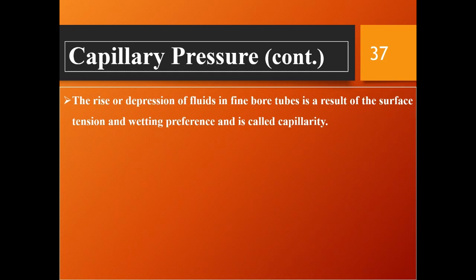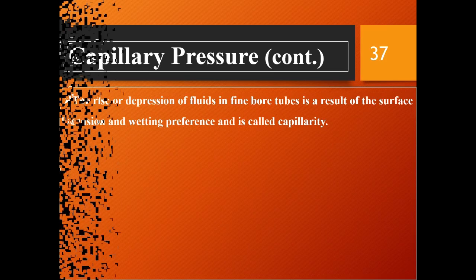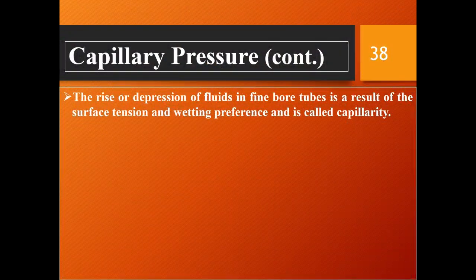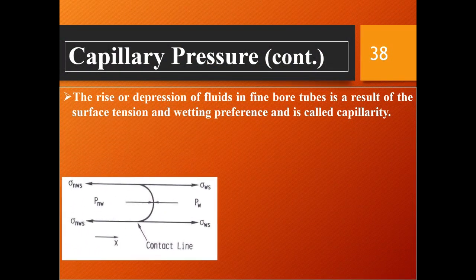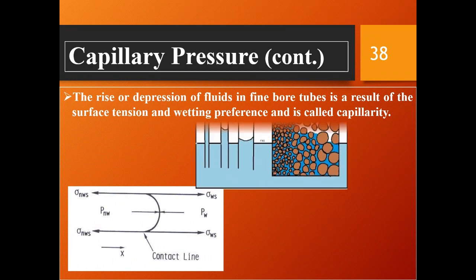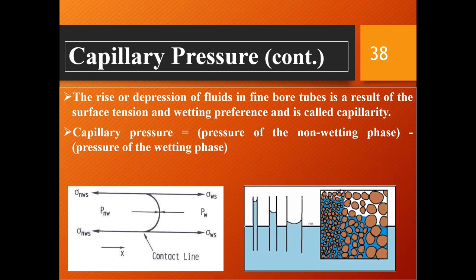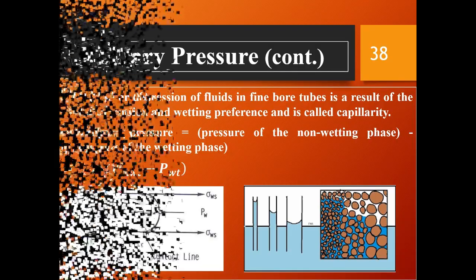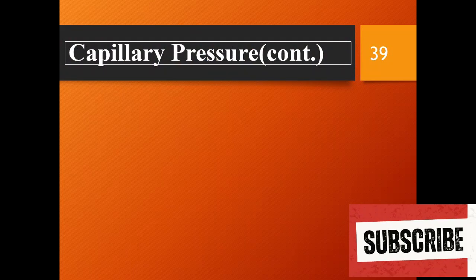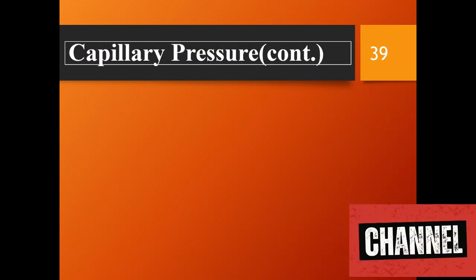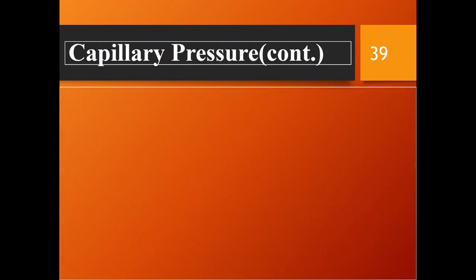The rise or depression of fluids in fine bore tubes is a result of the surface tension and wetting preference and is called capillarity. Capillary pressure equals pressure of the non-wetting phase minus pressure of the wetting phase. There are three types of capillary pressure.